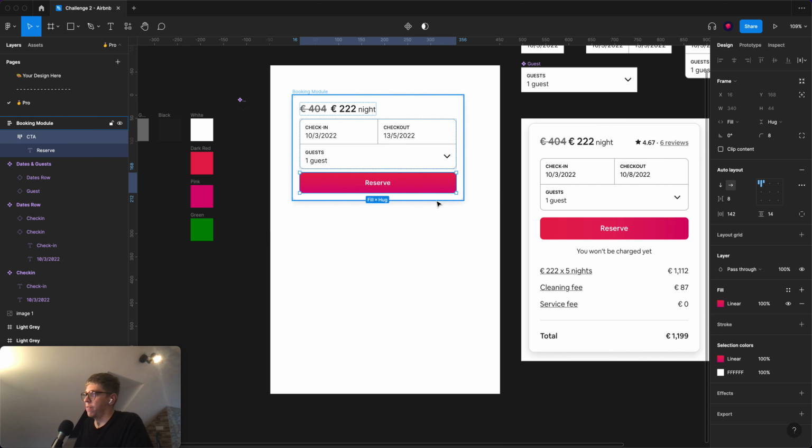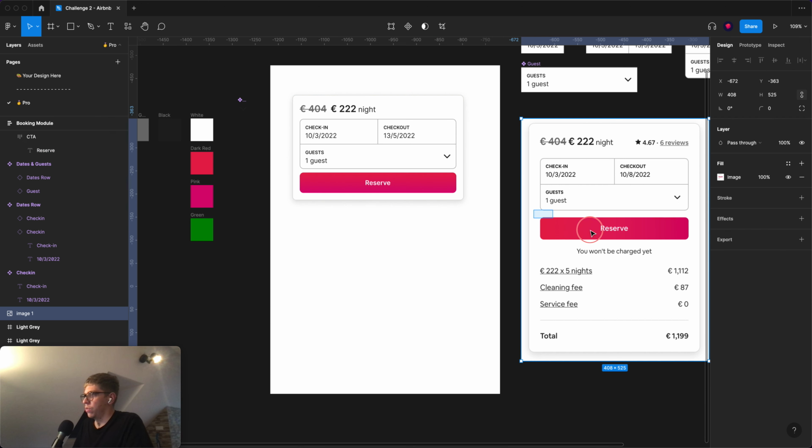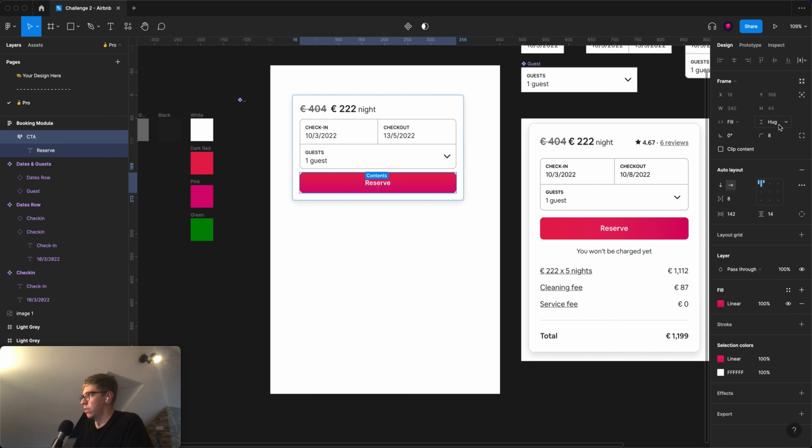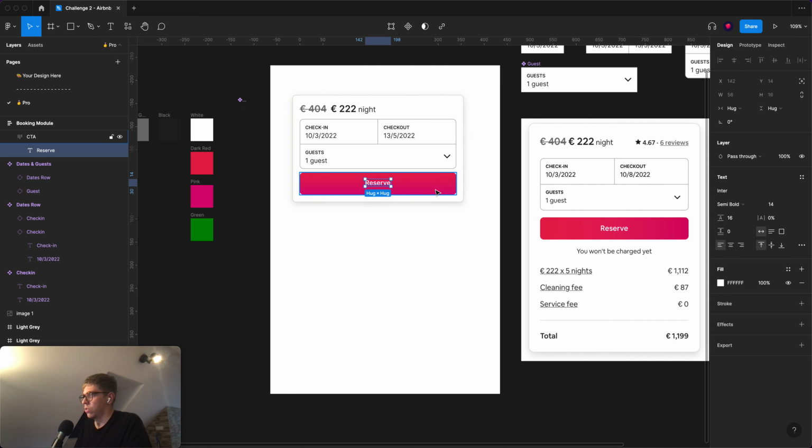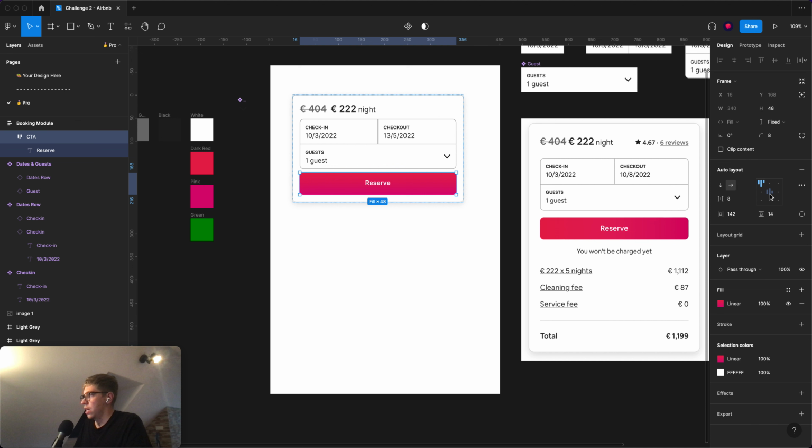That's because in the auto layout we have the padding set up, right? So if we want to have a fixed width, we just select it, go up here to vertical resizing, and then select fixed height, and then select the 48 pixels like that. And you need to align the text to the middle. So again, select it, and then press this one, the middle horizontally, the middle vertically. You can also now remove the paddings, and now this will kind of allow you to align differently.